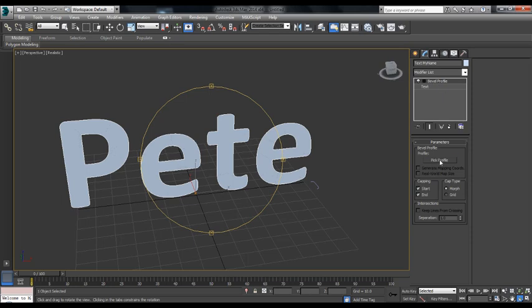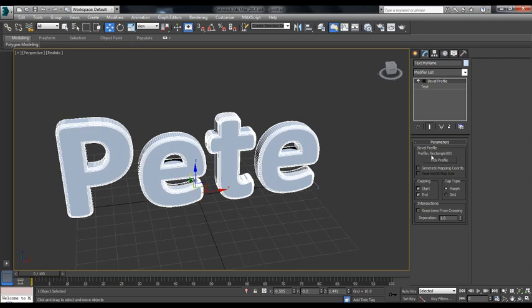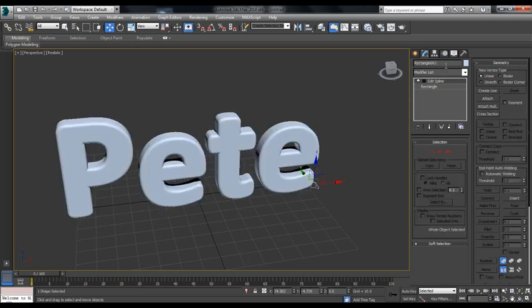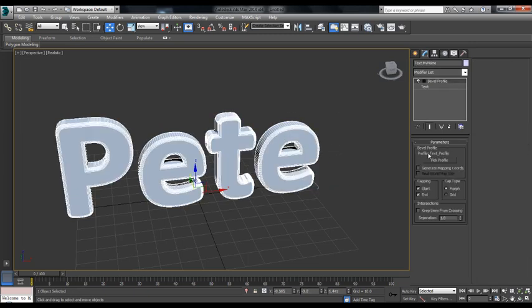So I'm going to go pick profile, and I'm just going to hover over here and just left click and select this shape that we made, and it appears here, rectangle 1. I'm going to rename this and call it text profile. Okay, now just going to go back to here, and you can see now our profile now contains text profile.